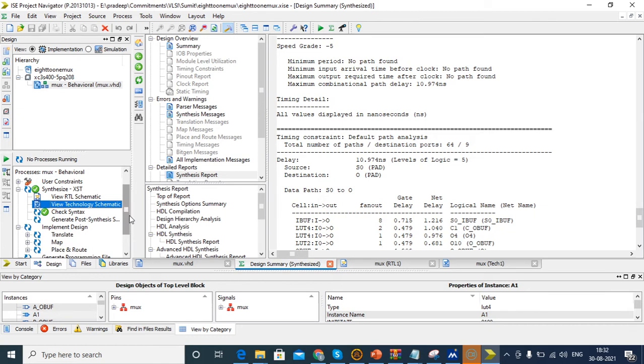So there are a lot of ways to develop the code. I'm using the logic case. There is another way also, that is the if and else statement. If you use that, then the usage of the input output and logic gates will get reduced, so that delay also will get reduced.